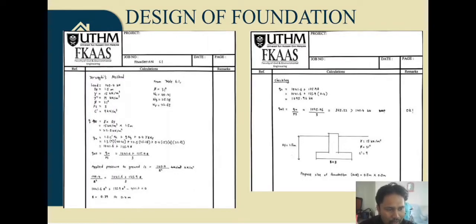Assalamualaikum. My name is Triatmo Dendi Santoso bin Sumar, and I will present on the design of foundation. We propose a spread foundation for this project, and we use the Terzaghi method to calculate the maximum allowable load and the size of the foundation. This is the calculation for foundation C1. The load from the column is 140.4 kilonewton.